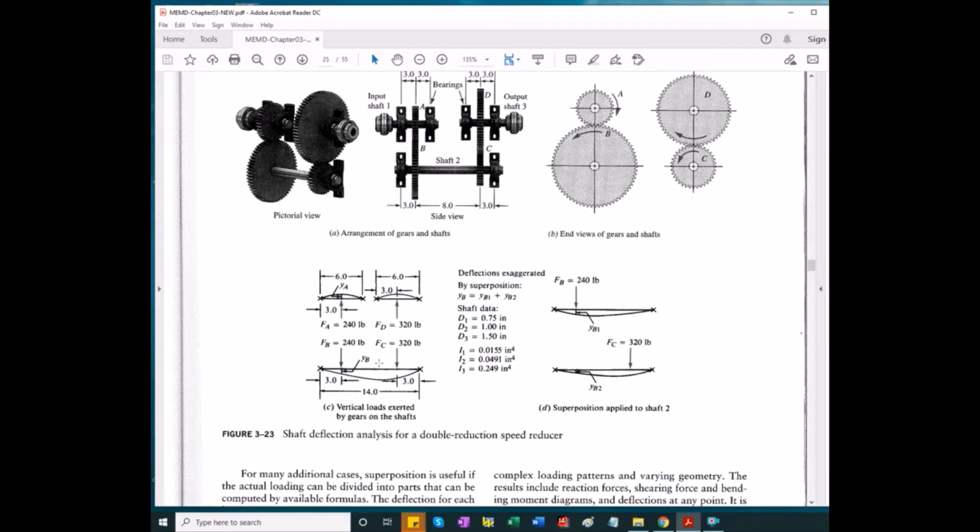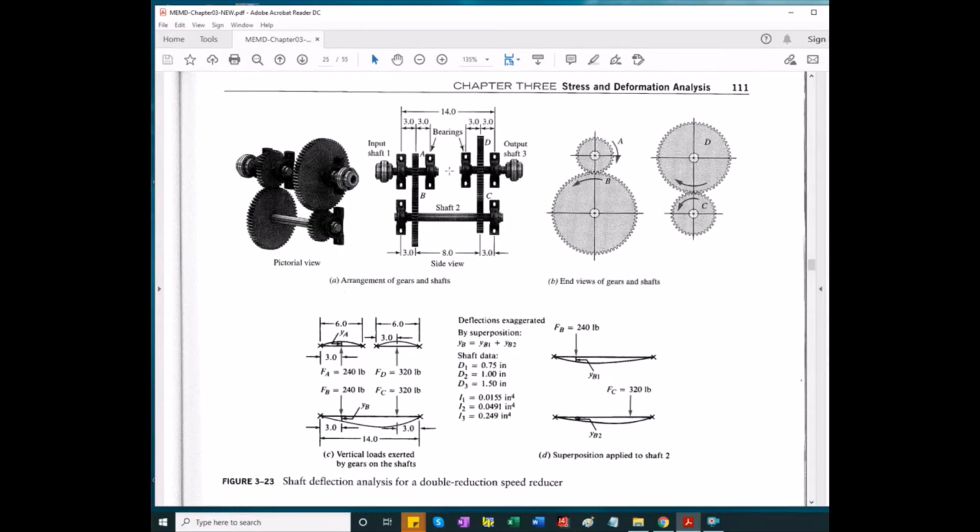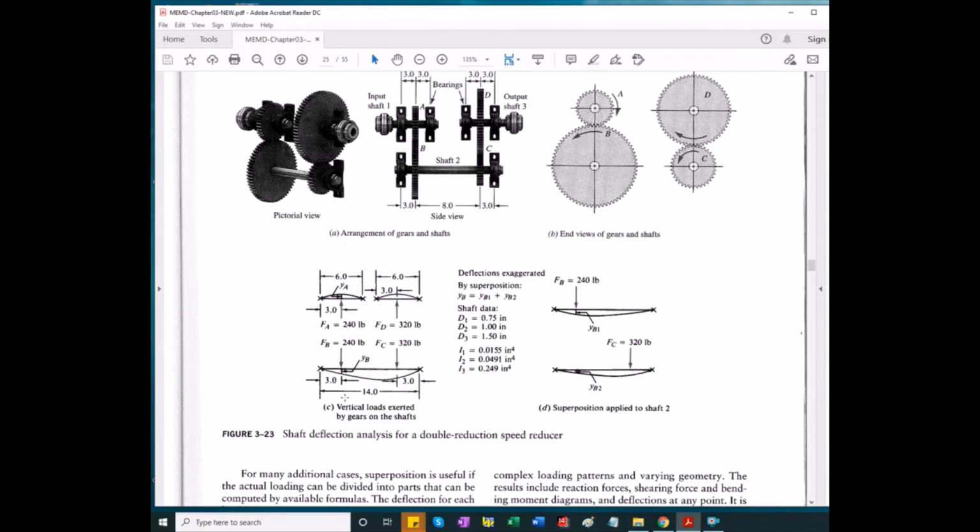And here's an example again for the one gear only carrying shafts, these two, and two gear carrying shafts, and it shows forces tend to repel the two gears. You can see they're away from each other, and the shaft deflects. And we like to know how much this deflection has to be limited.